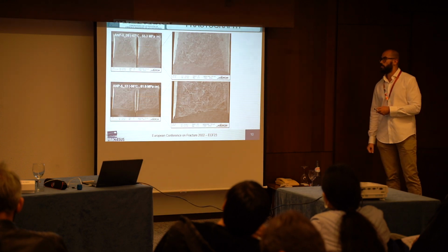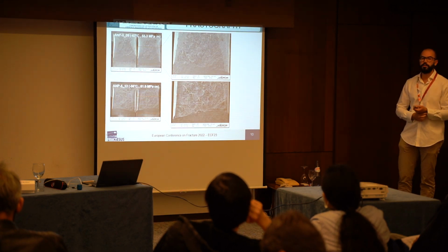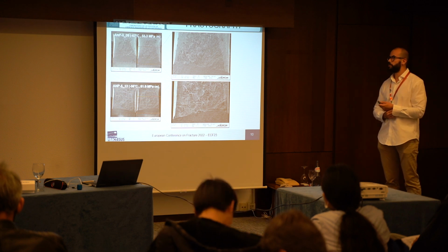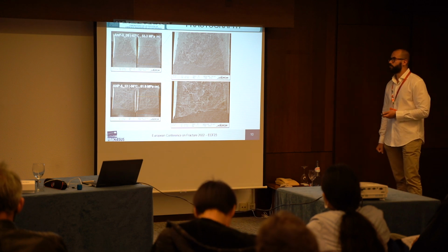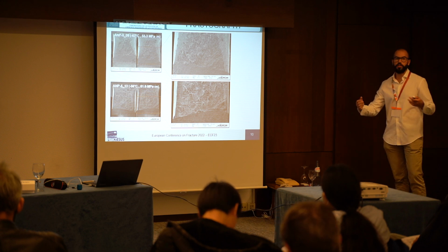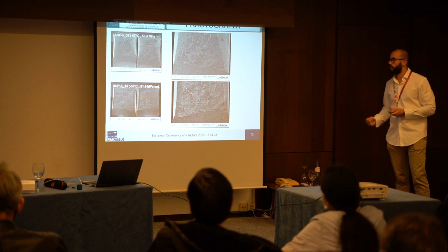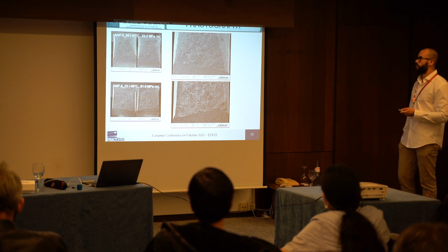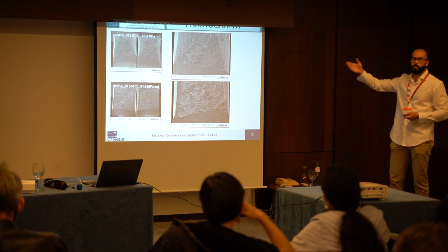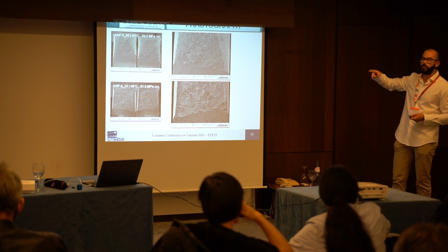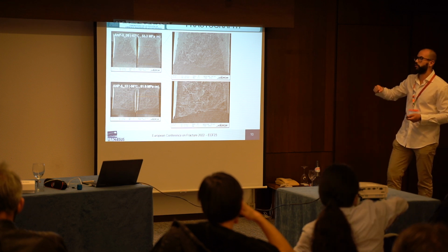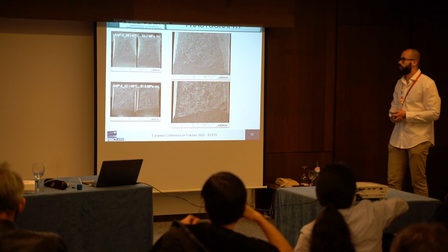One important job here is to analyze the fractography of the mini-CT specimens, because we need to check if the assumptions of the master curve approach are fulfilled with these mini-CT specimens. I have put a couple of examples with two different temperatures and two different fracture toughness values.